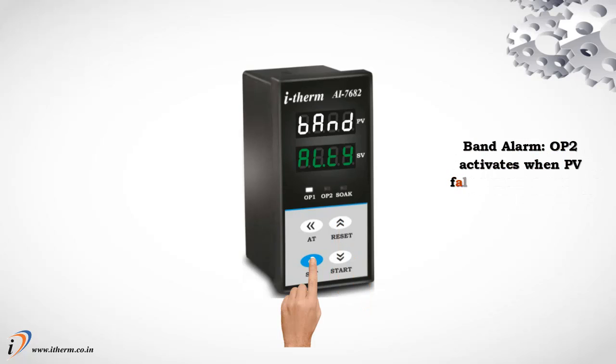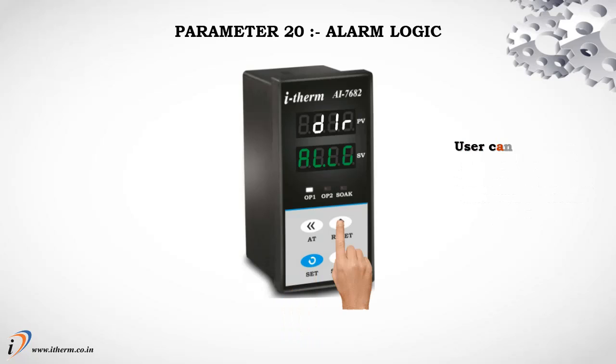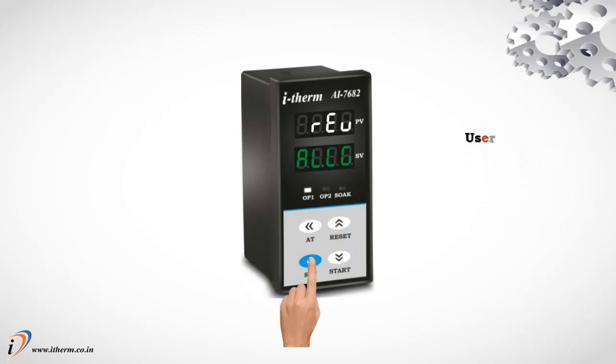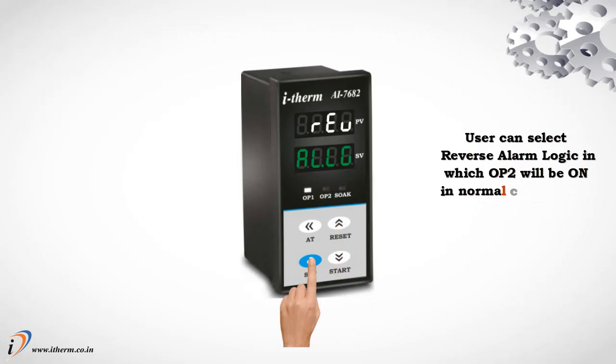Band alarm, output 2 activates when process value falls outside the band with respect to setpoint 1 in either direction. Parameter 20, alarm logic. User can select direct alarm logic in which output 2 will be on under alarm condition, otherwise off. User can select reverse alarm logic in which output 2 will be on in normal conditions, and will be off under alarm conditions.